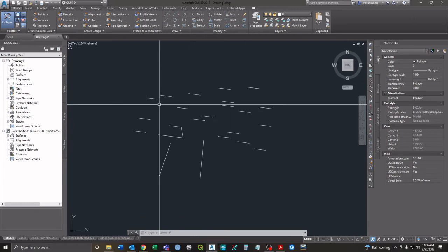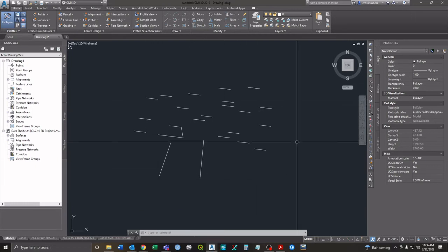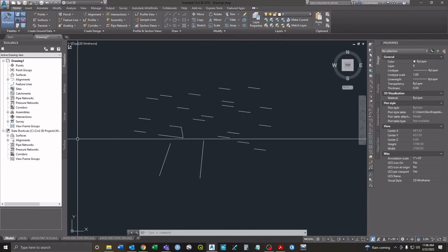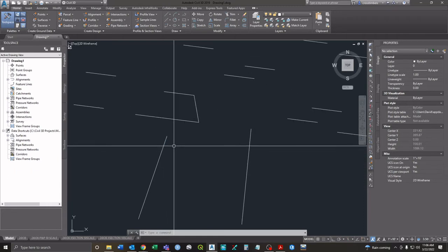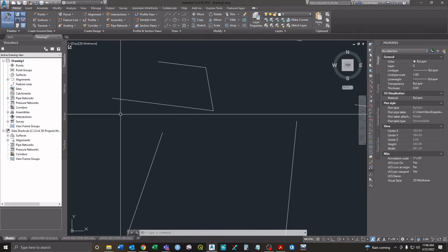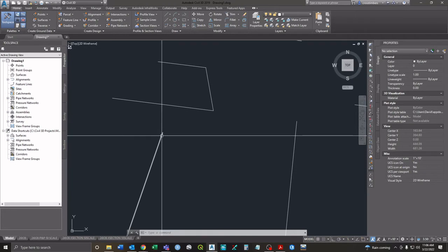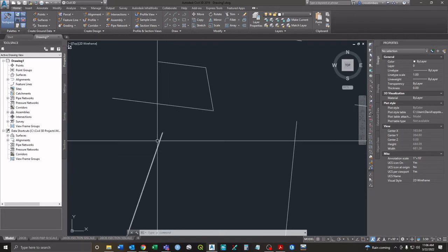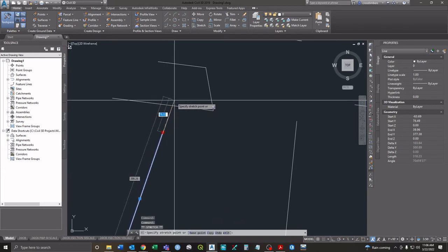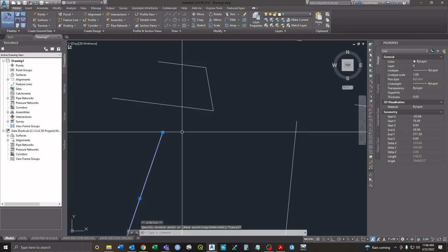So pretty much 90% of what you're going to be doing is lines and polylines. There's really not a whole lot of need to do other things. I will show you this real quick because it's basically the opposite of the trim command. It's the extend. So say we want this line to match up here, but at the same angle and everything. We could add the grip, but trying to match that exactly perfectly is kind of difficult, and then to get it right on here.